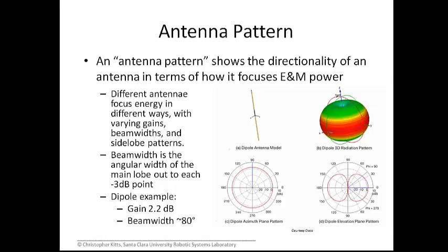So along the axis of the wire, you have some attenuation, but everywhere else you have pretty strong broadcast. And because you have good signal going to most of the region, the equivalent gain is fairly low. But the point of the diagram is to show how you would have the conversation about the beam pattern, the gain of a particular antenna, and how it is physically oriented with respect to the mechanical installation of the antenna.